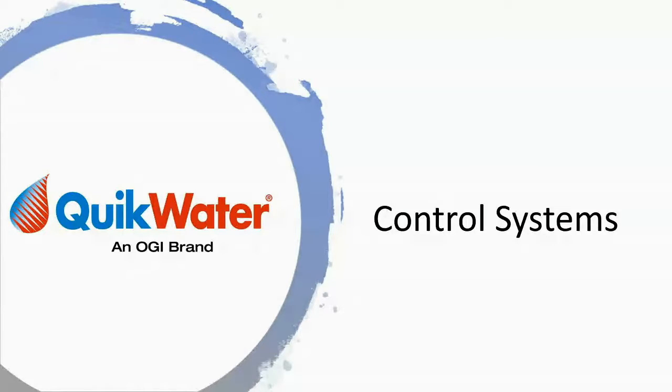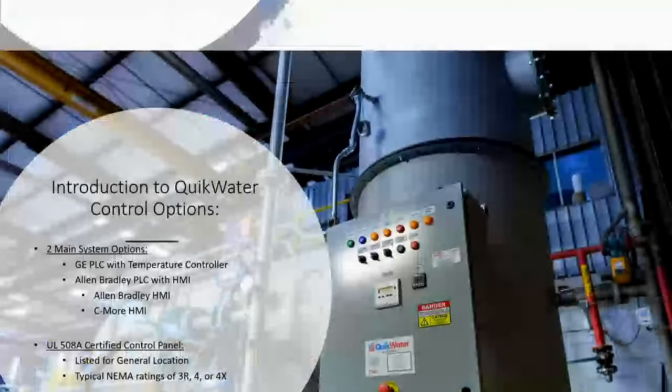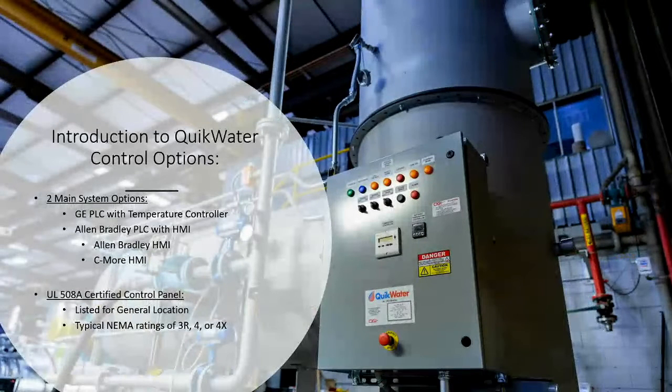Good afternoon, everybody. I'm going to talk just a little bit about our QuikWater control options and what those systems can do. We're just going to talk about our two main systems today: the GE PLC with the temperature controller, which is what you see in the picture on the screen right now, as well as our Allen Bradley PLC with an HMI. We do offer two different HMIs, an Allen Bradley PanelView HMI as well as a Seymour HMI. All of our control panels are UL 508 certified. They're listed typically for general location, as well as having NEMA ratings available for 3R, 4, and 4X.